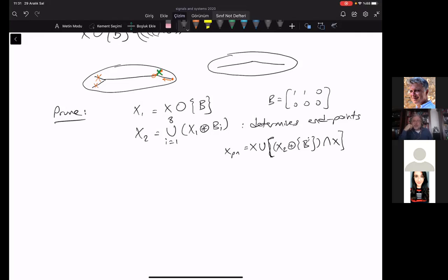That's digital signal processing, which is very important for image processing too. In two dimensions it is a very generic way of designing filters which will eliminate some information, which will stop some frequency content, and pass some other frequency content in two-dimensional frequency space. But we didn't design them. We didn't design any gradient filters. I have just given you a few gradient filters, like the Sobel operator and so on.